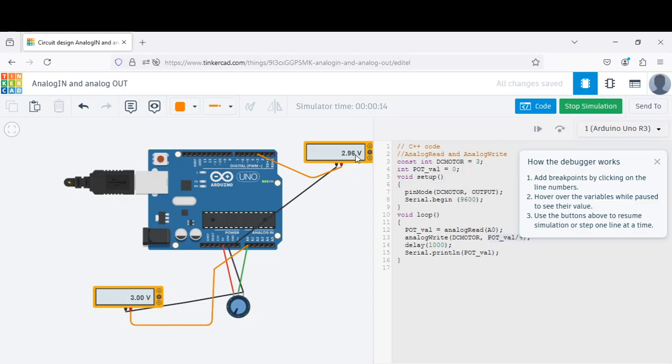So now if you change the position, see here, it is 3, almost there. With that divide by 4, you may lose one position, or it's almost the same. Because when the read value is an odd number, assume that it is 343, when you divide by 4, a plus or minus 1 will happen. So because of which there will be a slight variation.